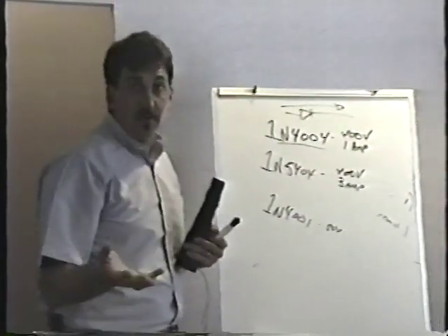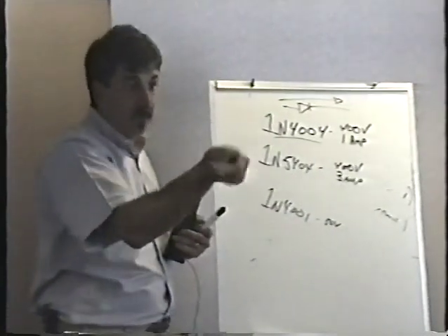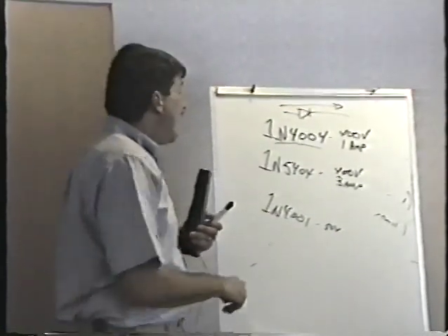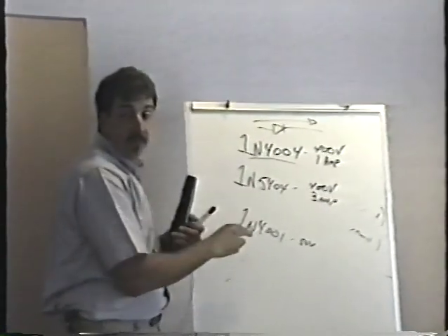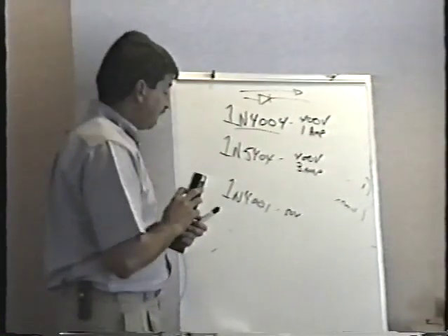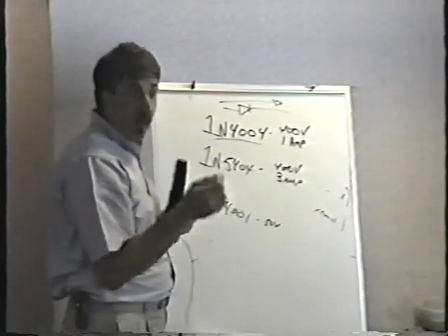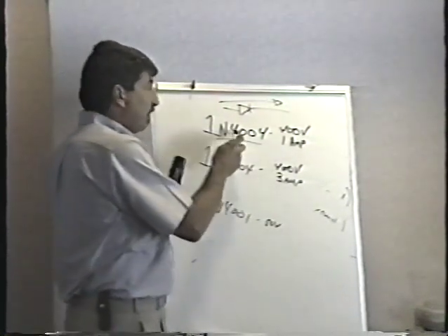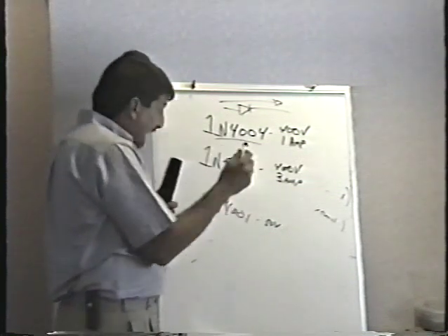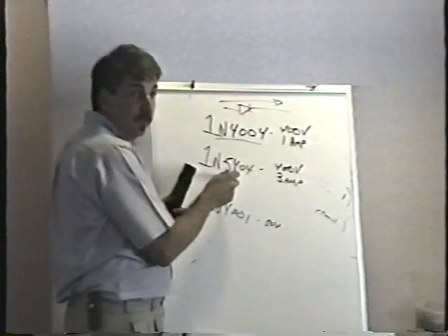So, again, my point is, if you have a diode that's only a 50 or 100 volt diode or something, and you've got a 400 volt diode, you can use that as a substitute. And you can also go up in current rating, as long as the voltage is adequate. So for instance, if I have a 1N4004 and it's bad, can I use the 5404 as a substitute?